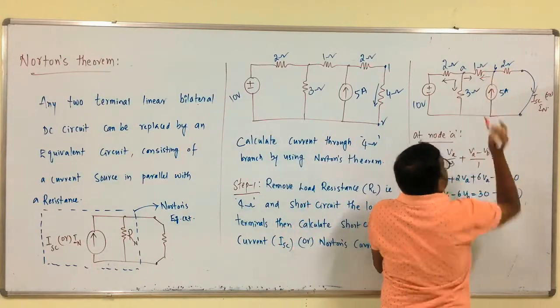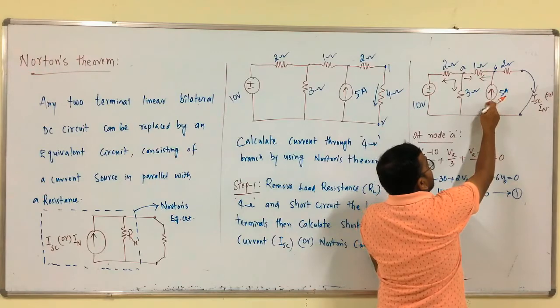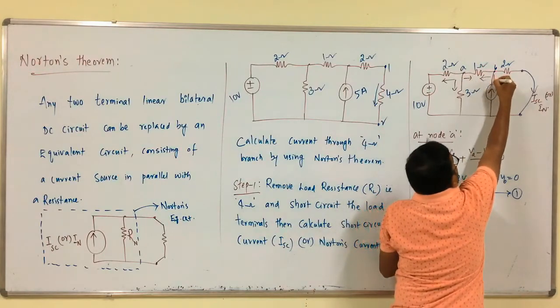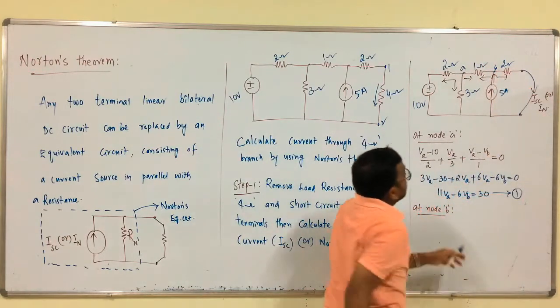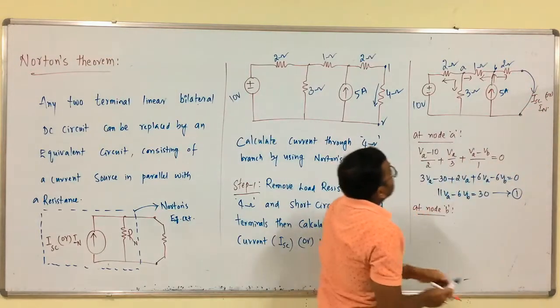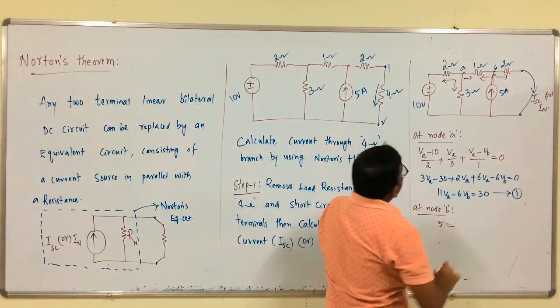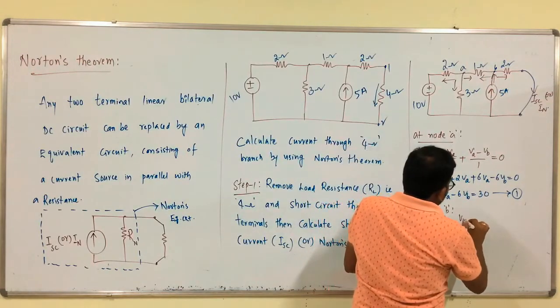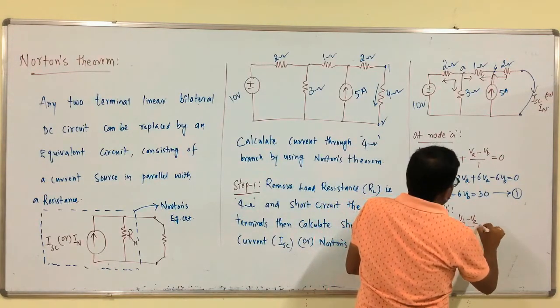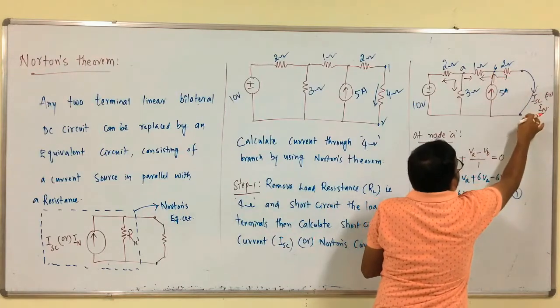from here this is leaving, but by default the current is entering towards the node; here it is leaving, because we have to calculate this current ISC. So, the entering current is equal to I5 and (VB - VA)/1 + (VB - 0)/2.